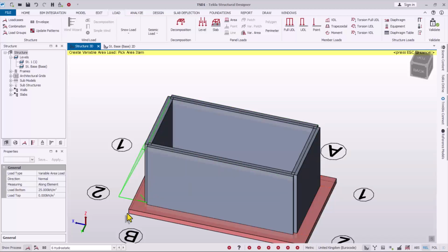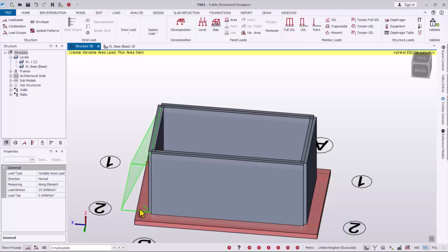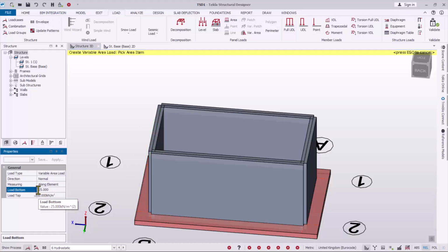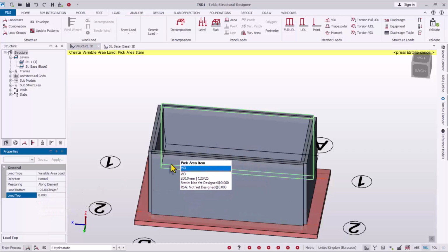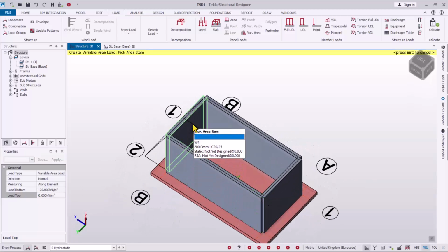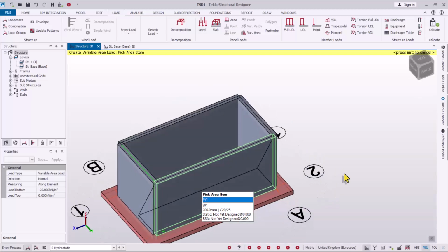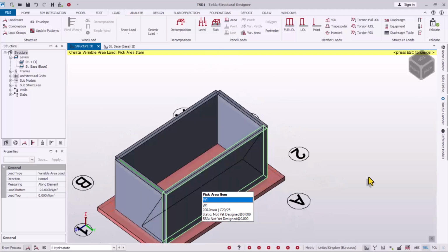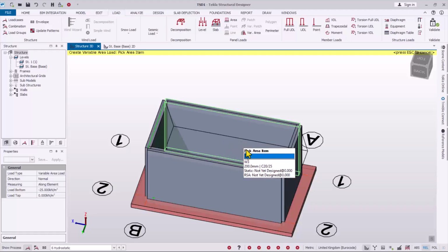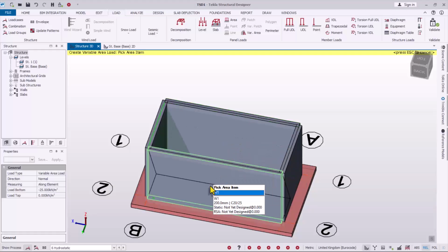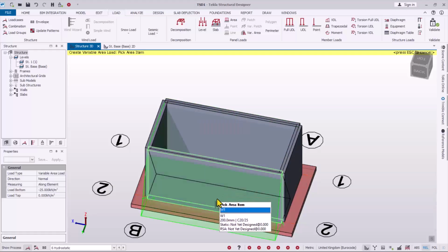So we click, and this is applying as outside, which means it is wrong. You can undo it from here and then click in these provisions, prefix this load with a minus sign. Just like this, and then after which you can now try to apply it again. You see this has applied inside successfully, which is the hydrostatic load. All right, so you can also check these directions. I think that is applying correctly.